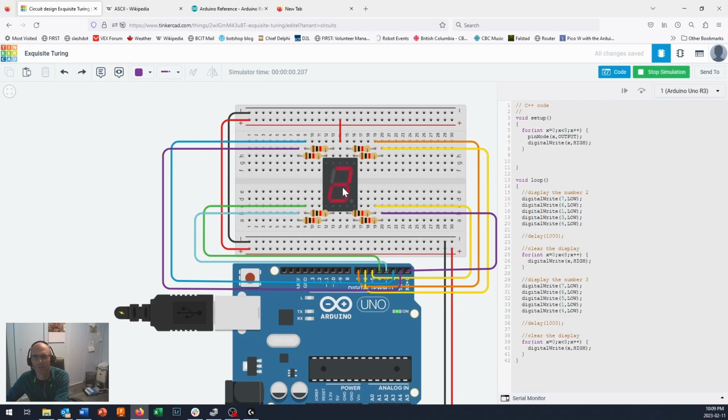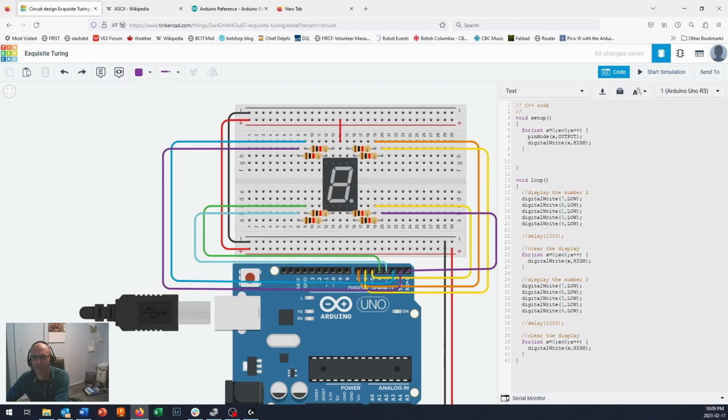you'd see a blurred thing like that. Now, these are actually turning on and off. You can see that some of them are a little bit dim. Okay, that's because they're turning on and off really fast. But to our eye, it looks like they're on all the time. So to show you that, all I did was add //. That's called commenting out a command.